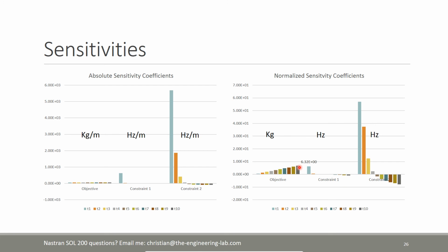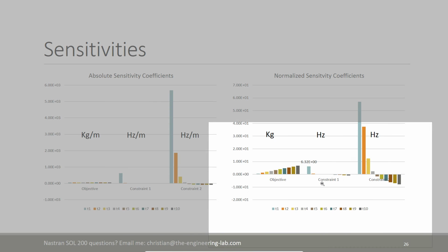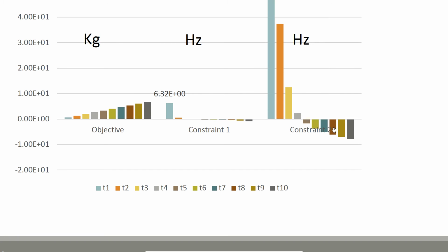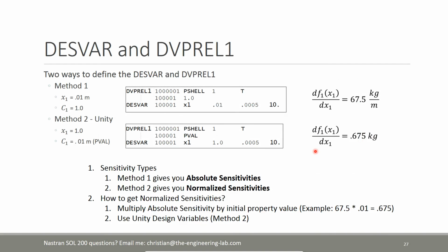Now we can consider the situation if we were to increase the thickness 10 parameter by 20%. It could be 30, 40, just to give you an idea of what would happen. Here I can see it will actually reduce the first natural frequency, G1, and it would significantly decrease the value for G2, which is our second natural frequency. Hence we have a negative coefficient here. That still might be a little difficult to really make sense of.